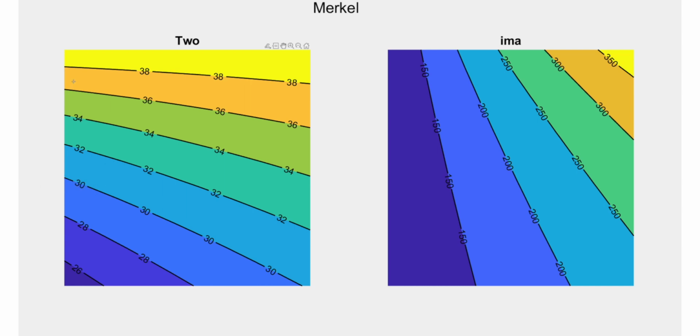You can see that the water in contact with the inlet air cools down a bit quicker than that further in the cooling tower, and on the right hand side we see the enthalpy of the air as it moves through the cooling tower, entering at 100% and then increasing to 150 all the way to more than 350 at the top part of the cooling tower, the air that is constantly in contact with the hot inlet water.